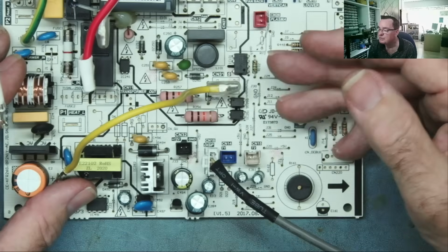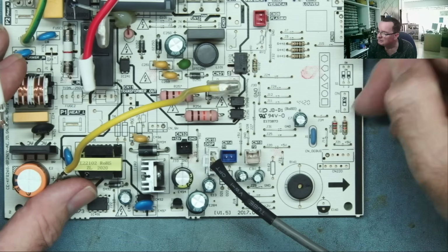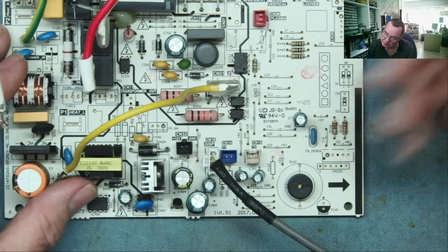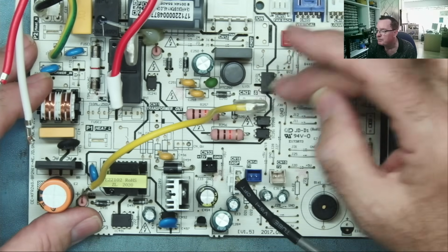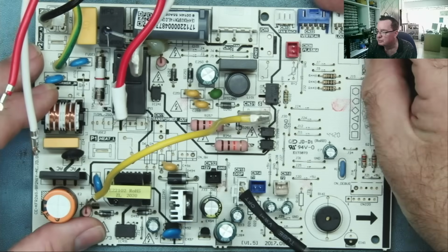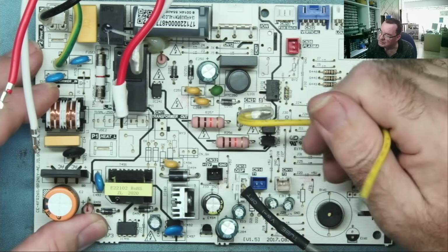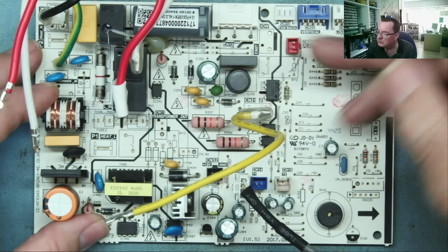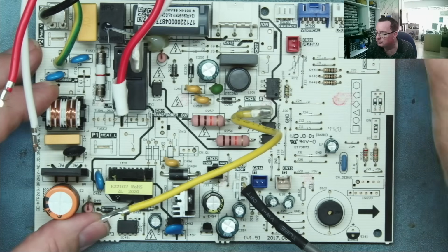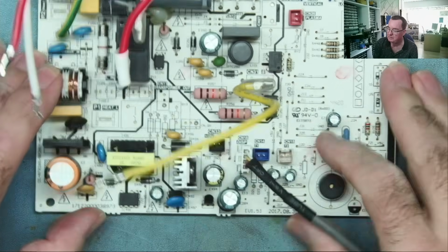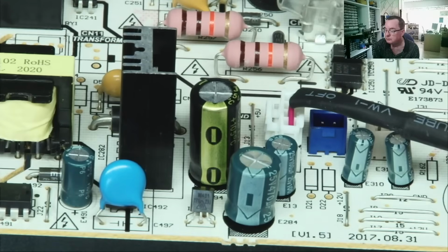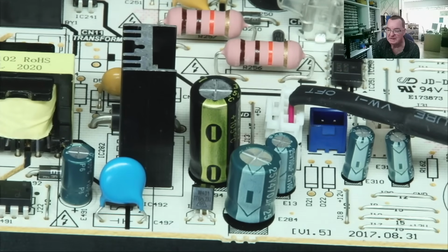We may be able to check resistors, but generally speaking, resistors burn up if they fail, and usually because something else has failed. Apart from high value resistors and power supply startups, they sometimes just fail. Diodes we should be able to check in circuit quite easily. Optoisolators, again, we should be able to check fairly easily. What's this thing down here? W431, that's a TL431, we can easily check that as well.